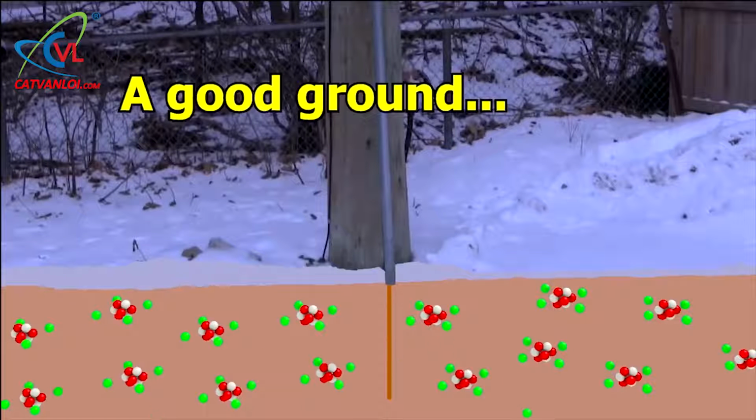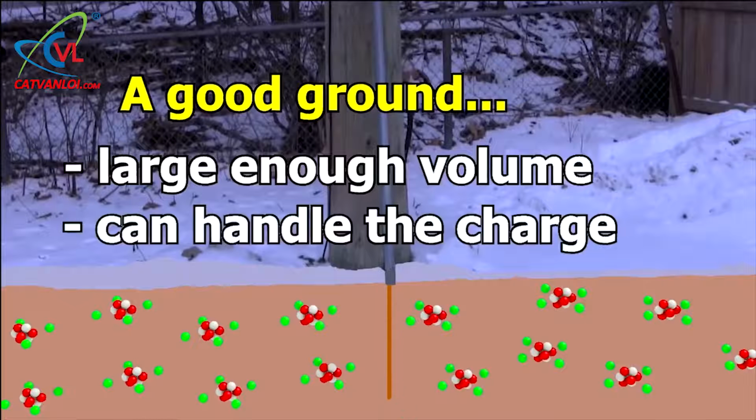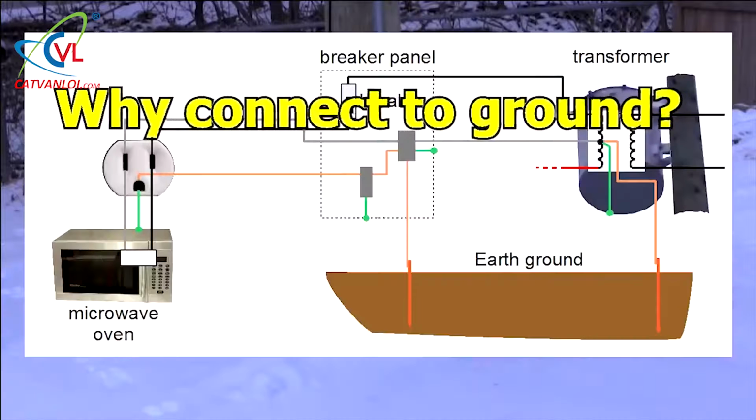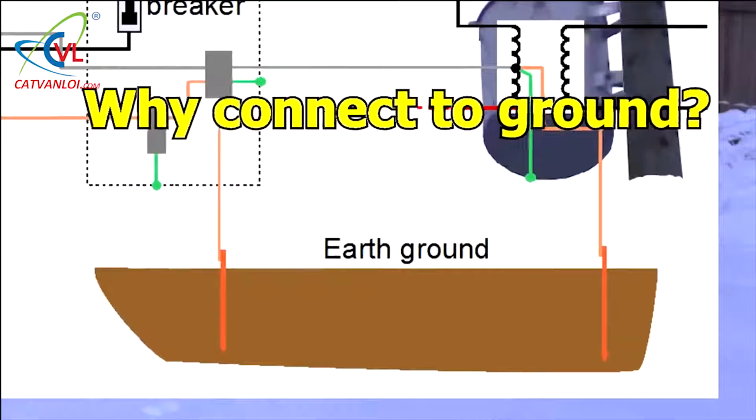So what's a good ground? A good ground is one that has a large enough volume that it can handle whatever charge you're trying to give it without it ever becoming very charged. Now back to why we're connecting wires all the way to earth ground.